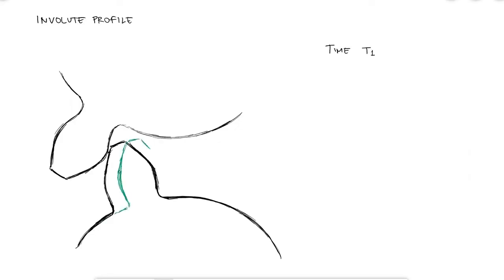inch. The involute profile refers to this very precise shape the tooth has. This shape would guarantee that the point of contact between two teeth, one from each gear of gears in contact, occurs where the two surfaces are tangent to each other. The reason I say would guarantee instead of stating it as a fact is that this only happens for perfectly formed, perfectly smooth, and infinitely rigid teeth, which of course is not the case.